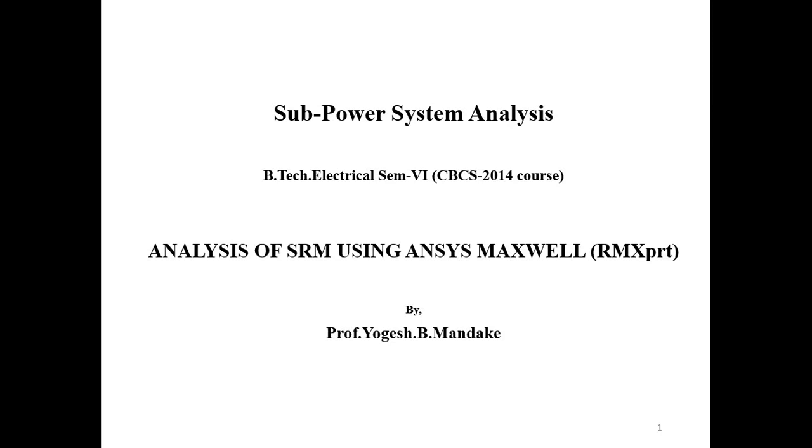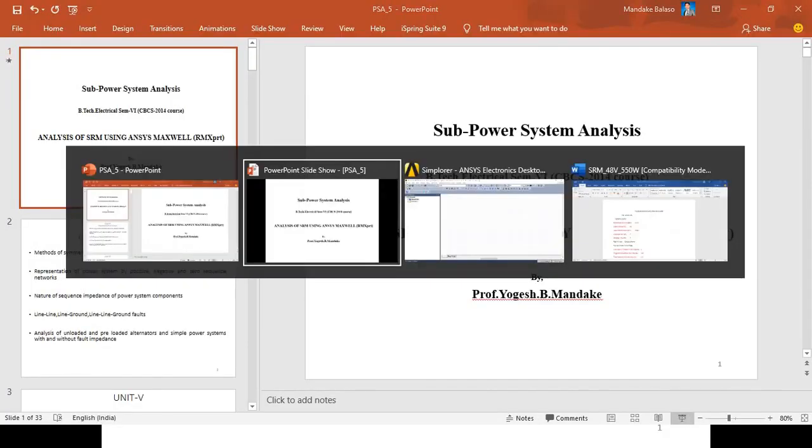In this case we had discussed how to design a 550 watt motor of 8x6 type, where 8x6 means 8 is the stator number of poles and 6 is the rotor number of poles, and how to design that 8x6 550 watt DC motor using the ANSYS Maxwell RMXprt tool. So we'll just revise that part, or we'll try to design the motor again in short.